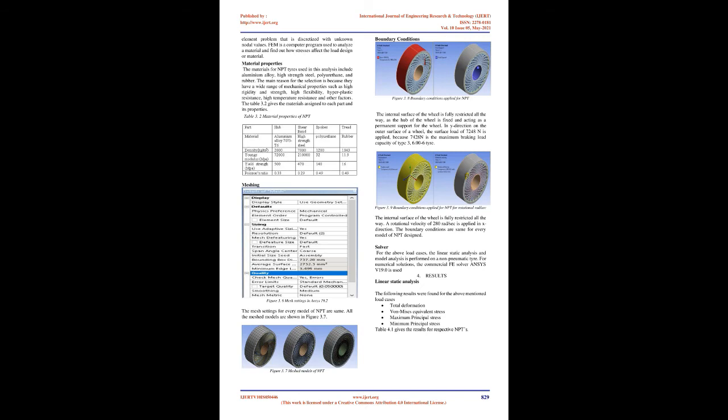Taking into account the non-pneumatic tire structure, spokes are compressed and tightened while they roll in cyclical loadings. Therefore, the localized stress of spokes must be reduced, which means that spokes must be fatigue resistant. In this project we considered non-pneumatic tires based on circular pipe, spline, and double spline. The spokes of non-pneumatic tires are crucial for rigidity and resilience under cyclic loading of compressive stress. The challenge is to design highly rigid, highly durable materials.